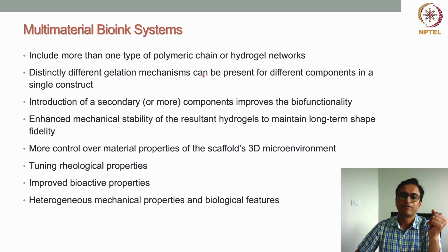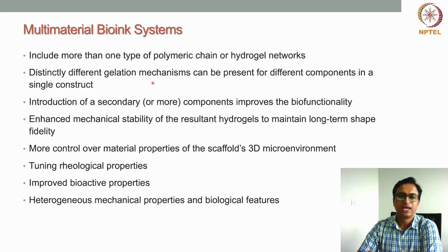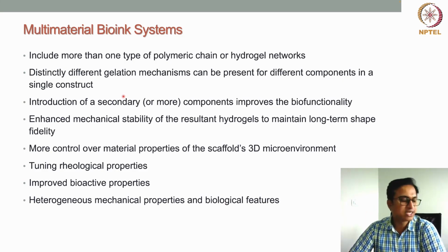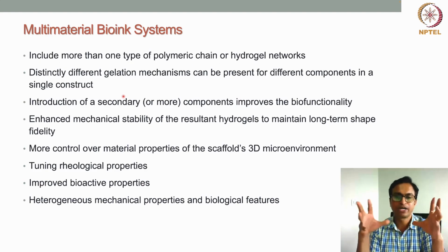So in that way, we can improve the print fidelity, the mechanical post printing mechanical properties, all these things, by introducing distinctly different gelation mechanisms. Other thing is, if your Bioink is made up of one component, and you include another or secondary component that brings a few biofunctionalities, then that will improve the biofunctionality of the whole Bioink, right?